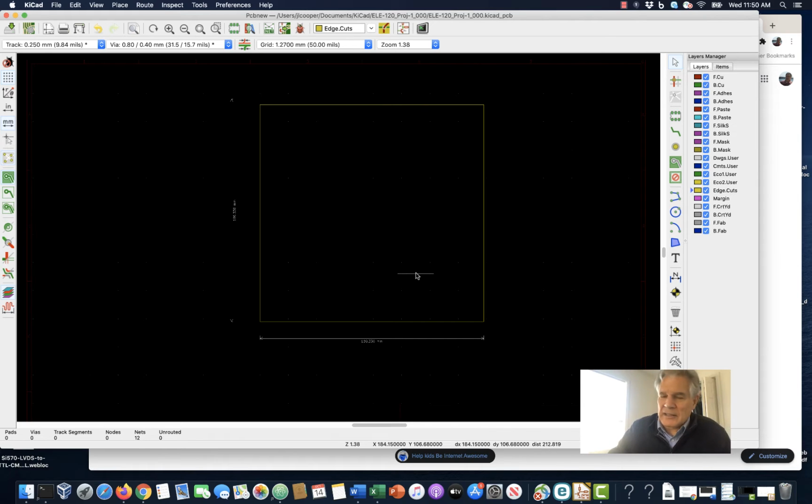You can fit a lot on that size board, and you can get 10 of those boards made for $5. And if you want the shipping, so you get it in about a week to 10 days, it's maybe another $17. So for 20 to 22 bucks, you can have 10 boards made. That would be two-sided, silk screen on both sides and solder mask on both sides. And of course, any vias going through the board would be plated through, which would meet all our requirements. So let's start out with this as our board.